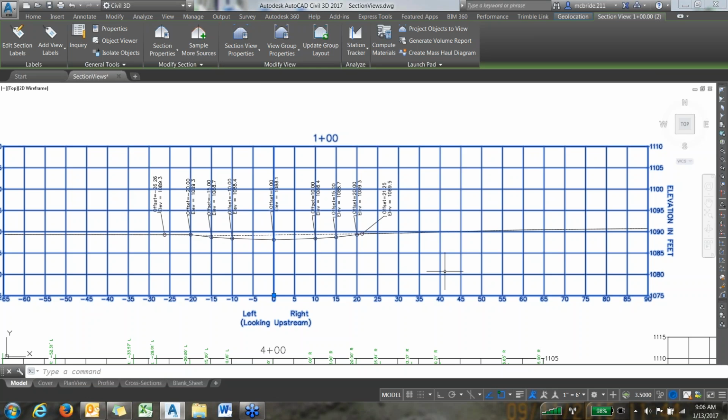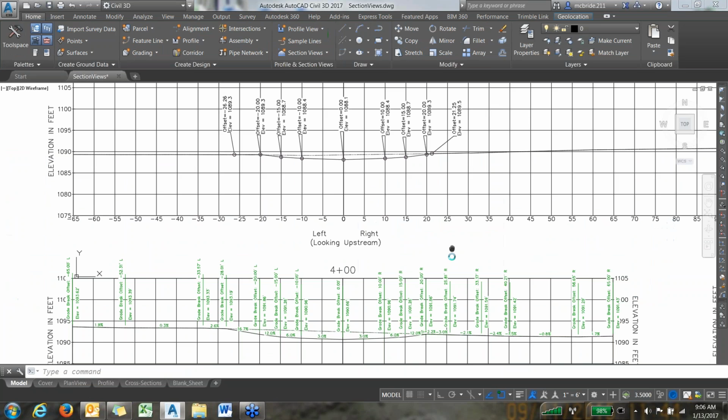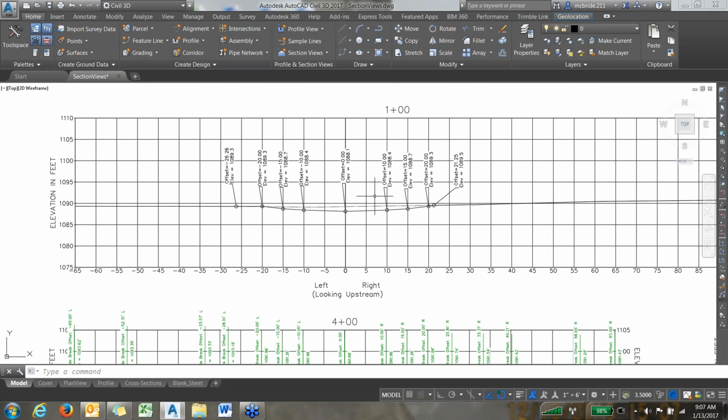Okay, which is fine. If you want to put this on the plan because it's easier to read, that's okay too. I mean, it's really based on your preference. I have all the information here I need, all the elevations and stuff, and this should be scalable. So if you put these on the plans, you know, this is 1:1, so you should be able to put it on scale where you can say 1 inch equals 5 feet on here, or however you do it. But it should all be scalable to where you can use some sort of ruler or scale on this to get certain elevations if you need to.